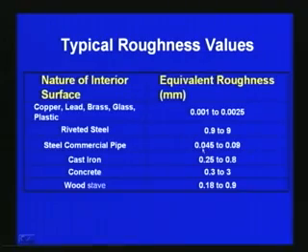So, for different materials, depending upon the material considered and the finishes given, the roughness height changes. So, the equivalent roughness height changes, and accordingly the friction factor also changes as given in the various relationships and methodologies which we discussed, like Moody's diagram or the Colebrook equation. So, depending upon the relative roughness, the friction factor changes, and as the friction factor changes, the head loss also changes. All these important aspects we have to consider in the design of pipe flow systems, while considering a typical system.